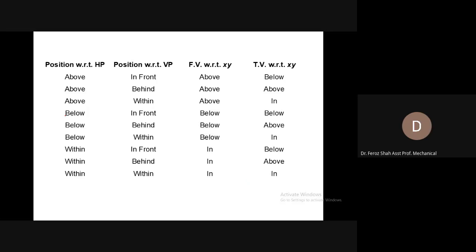If the point is below the horizontal plane, its front view will also be below the horizontal plane. If the point is within the horizontal plane, its front view will also be within the horizontal plane, within the XY reference line.